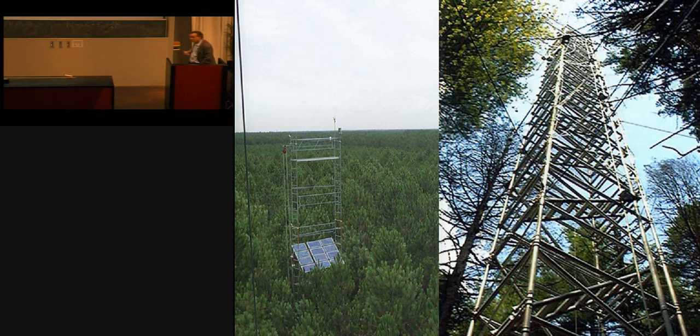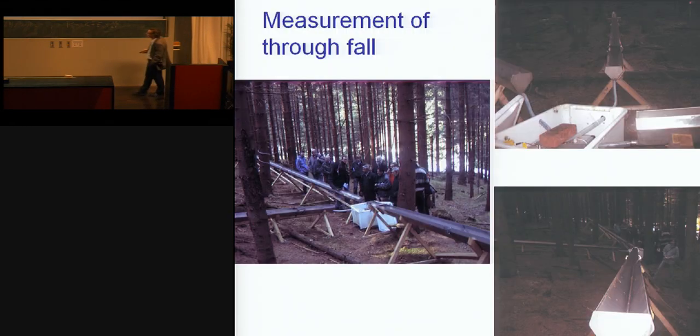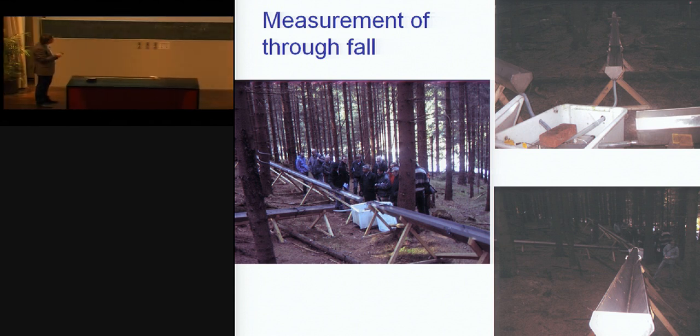Now, the gentleman asked me already before the break, how do we measure throughfall? I said if we would measure with different rain gauges here below the canopy of this nice plastic plant, it depends on where you put the rain gauge. Everywhere it's different. To account for that, people measure in these kind of throughfall gauges. These are long, open pipes, and they collect all the water falling into them and then send it down to a measurement device where they measure the volume of rain.